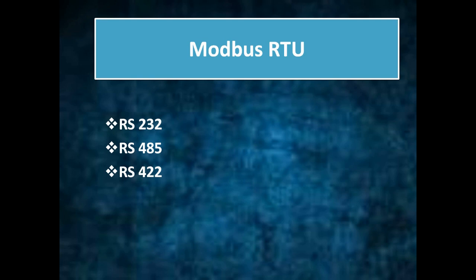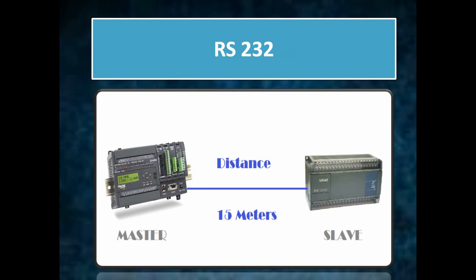And in Modbus RTU, every device has its own slave ID. That's how you're gonna call the device when it's required. For example, we give different people names to call them, like Amir, Sohail, something like that. So in case we need to call the person, we will call them by name. But in a Modbus RTU environment, if we need to call some device there, we identify the device by device ID.